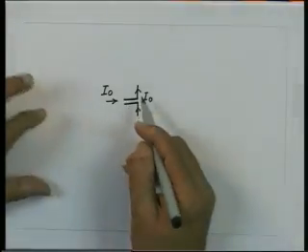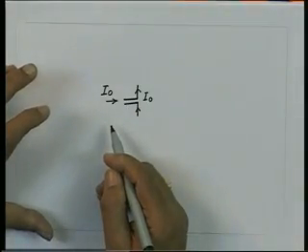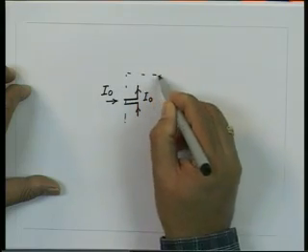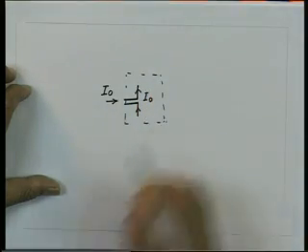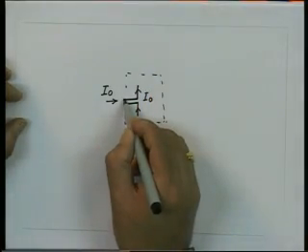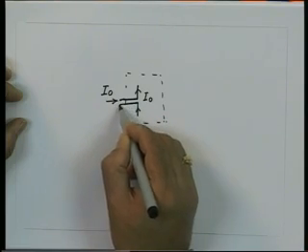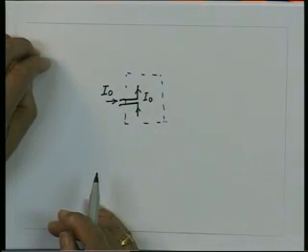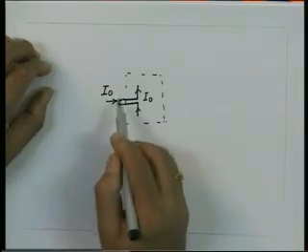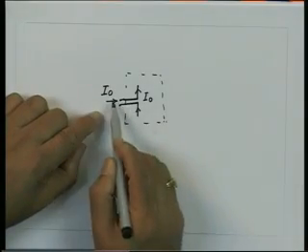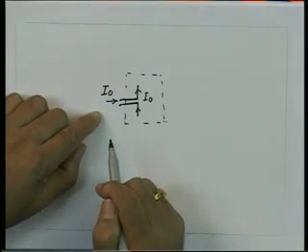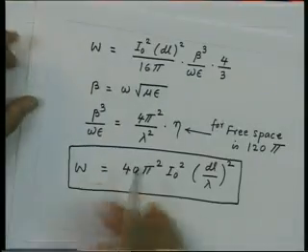So, if I see from the input terminal side, since the antenna is radiating and this power is now going away from the structure, if I enclose this antenna in a black box, if I treat it like a black box and just observe the characteristic only on the terminal of this antenna, it will appear we have a current I 0 going inside the terminals of the antenna and so much power is radiated by the antenna. That means this box has consumed so much of power.